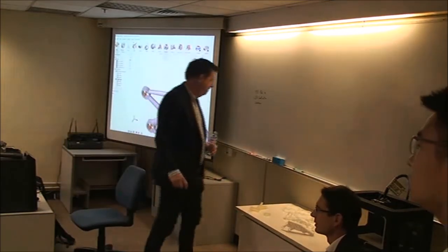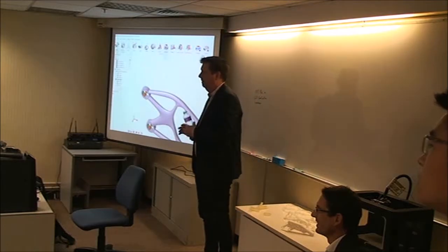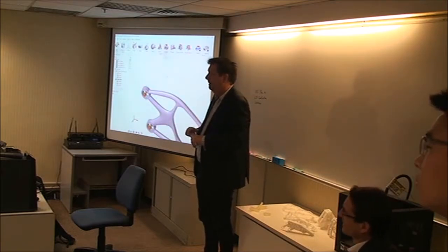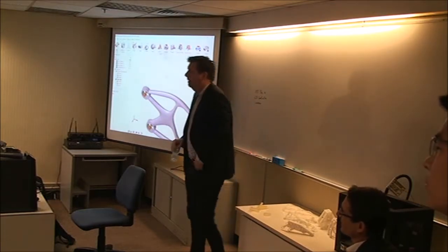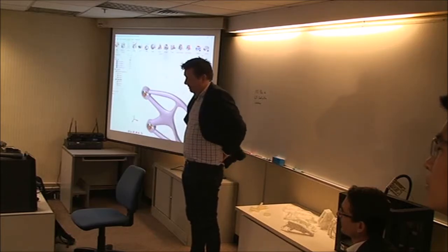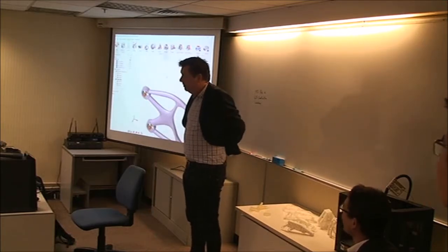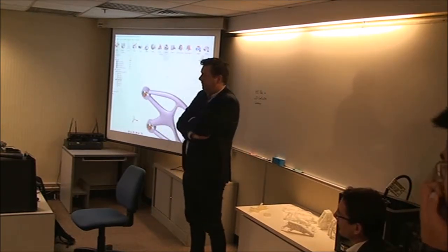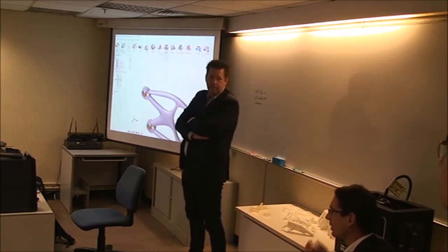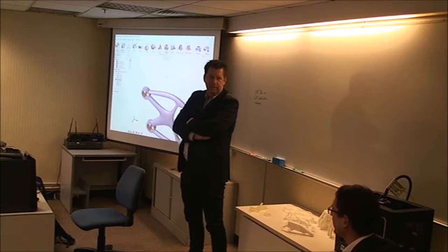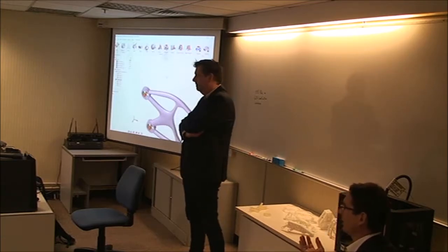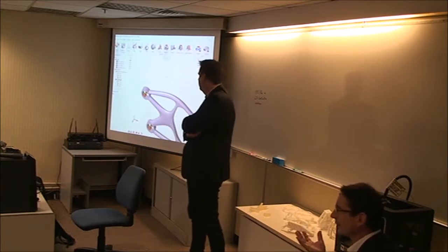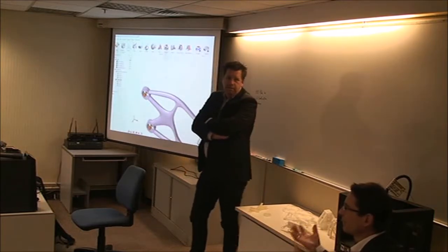What's the margin of safety in your design? Because this is just software, right? Yeah. What is the percentage, the risk factor? It can be wrong. In terms of structural loading, you have a margin of safety. What is this margin of safety? Well, these are the points which can go wrong. You have to specify the loads, the accuracy of the loads. That is important on the one hand, and the stress target: what can the material sustain? You have to bring both together.